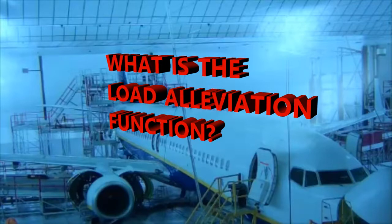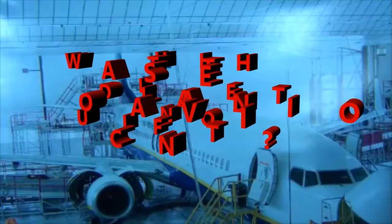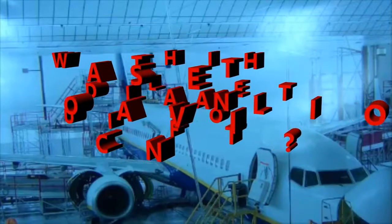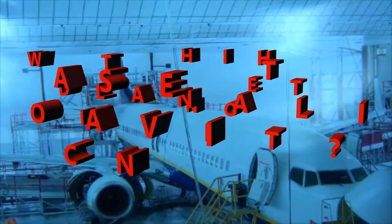And what it's doing is just modifying the span-wise lift distribution with the ailerons and our spoilers, upper deflections. So it's kind of reducing that for a little while. Basically, it's a way to keep the wing from bending too much. Okay, so it has some flexibility, but wherever they can utilize the other control surfaces to alleviate some of that, well, that's what we're talking about here. That's what that load alleviation function is doing. It's utilizing other control surfaces to help reduce any load that may be existing there on the wings.